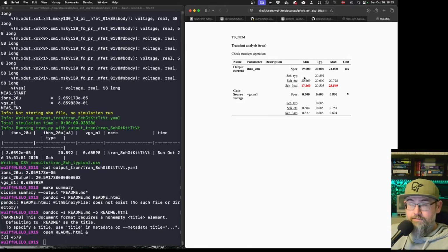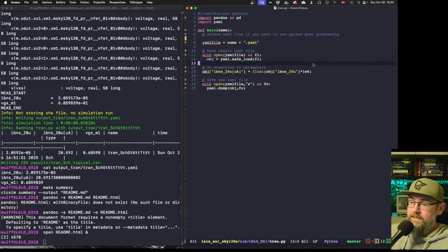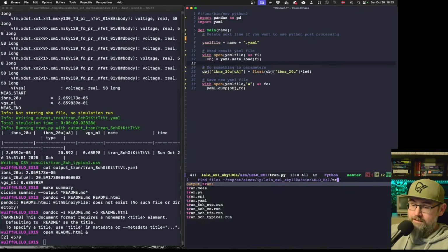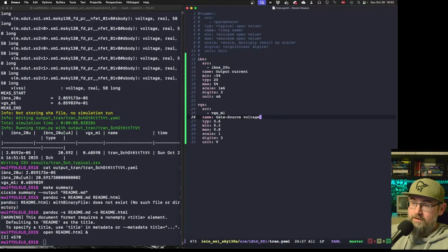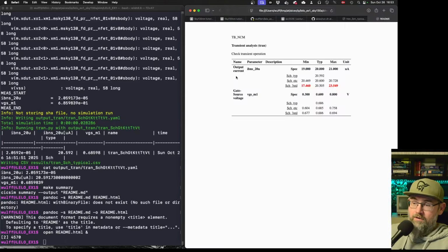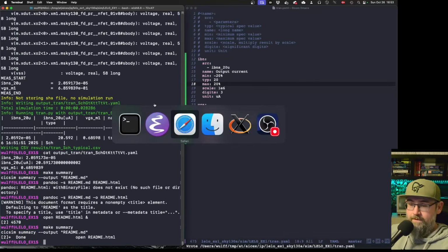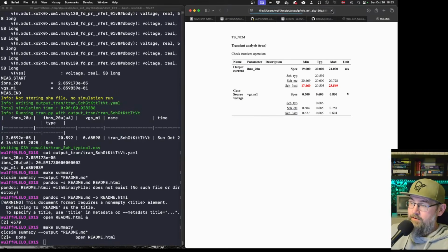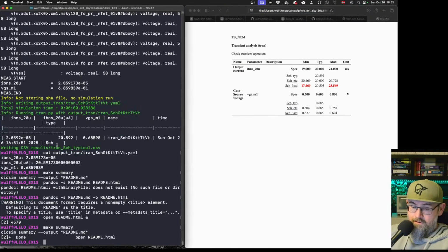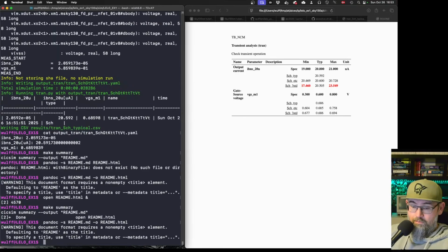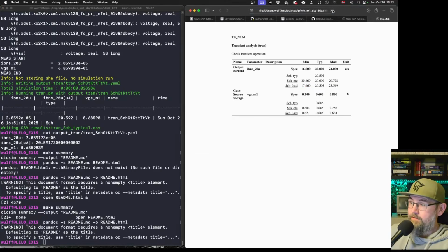There are multiple ways to fix that. One way to fix that is to go into the YAML file and say, well, I don't want 5%, I want 20%. You change the spec. And if I now rerun, oh, actually, I have to not just do that one, but do that one too. And now you can see it turned black.